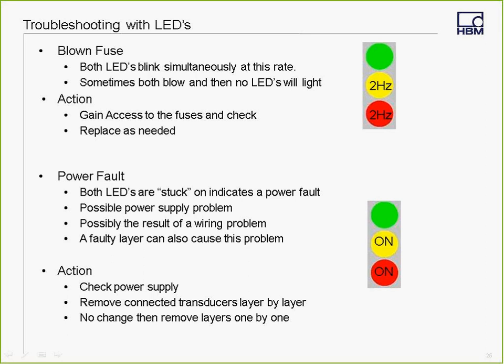Okay, other action would be to check your power supply, remove connected transducers layer by layer, and if there's no change, then you would end up having to remove the layers one by one until the fault clears. And obviously, if the fault doesn't clear, you have an actual power supply problem in that eDAQ, and it will need to be sent in for repair.